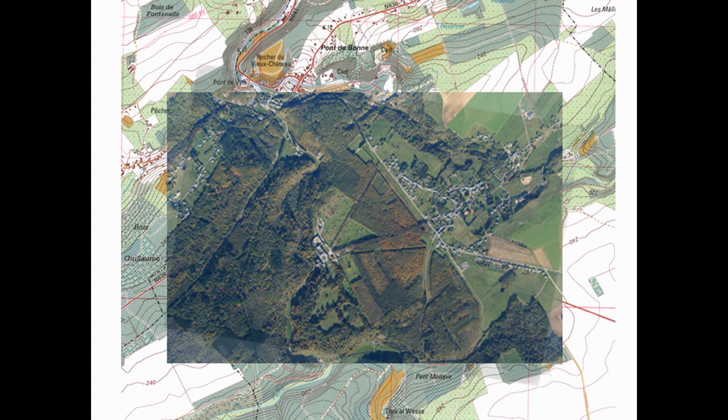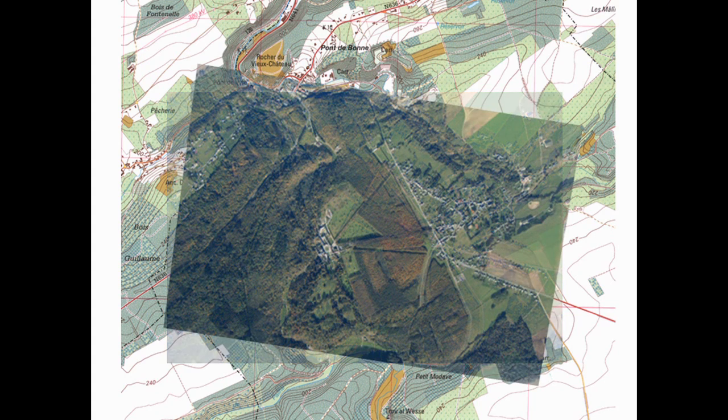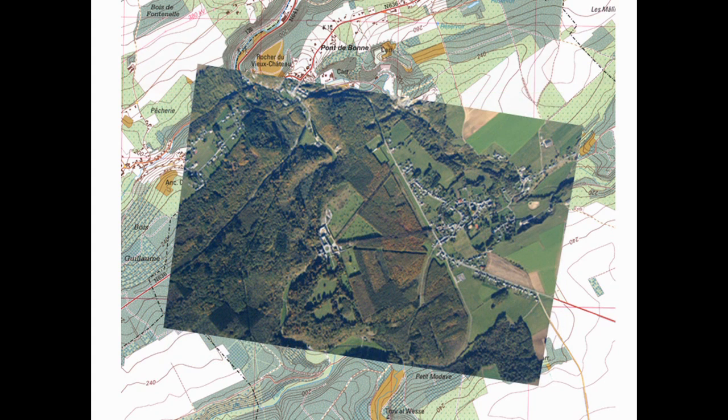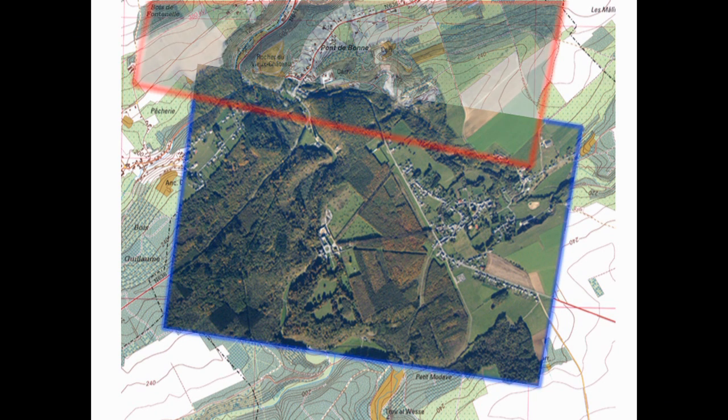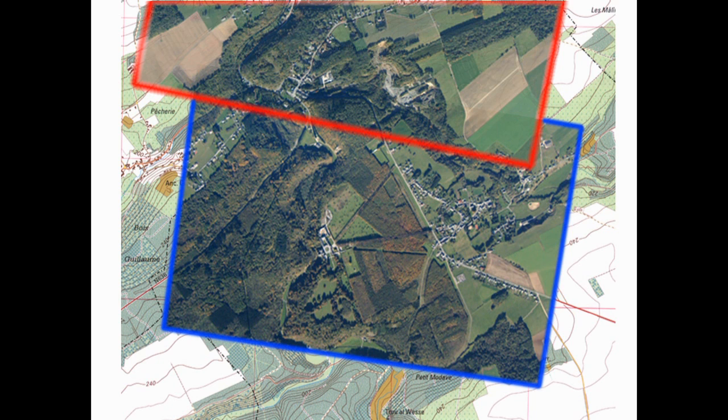Aerial photo cannot be simply used as a map. Each photo is affected by geometric distortions generated by the position of the camera, by optical artifacts, and, above all, by the relief of terrain. It is, however, possible to correct most of these distortions on each photo, then to merge these corrected photos to form a large mosaic called an orthophoto.